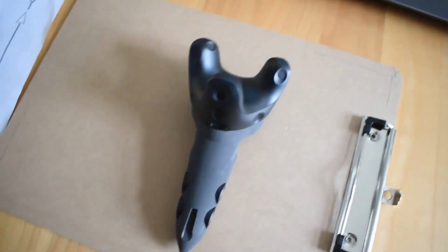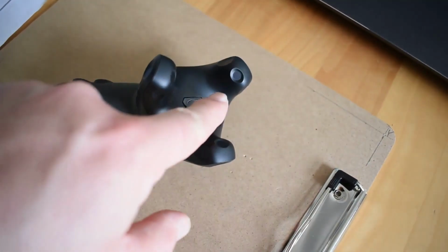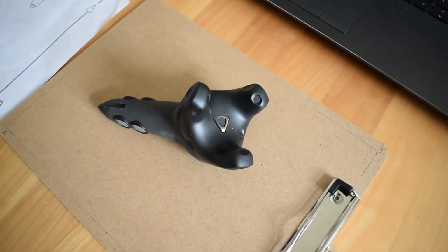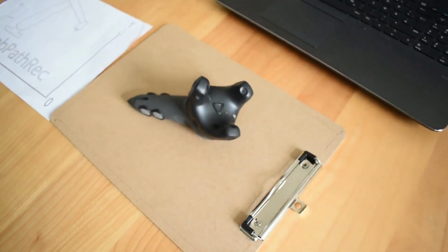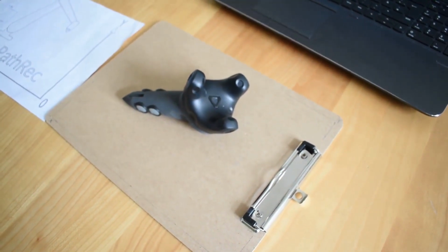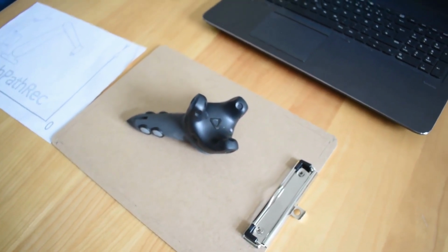I would like to explain some stuff about this device. So the small openings on the device are photodiodes, and we must hit at least 3 photodiodes with at least 2 laser beams so that we can figure out the correct position and orientation of the tool.